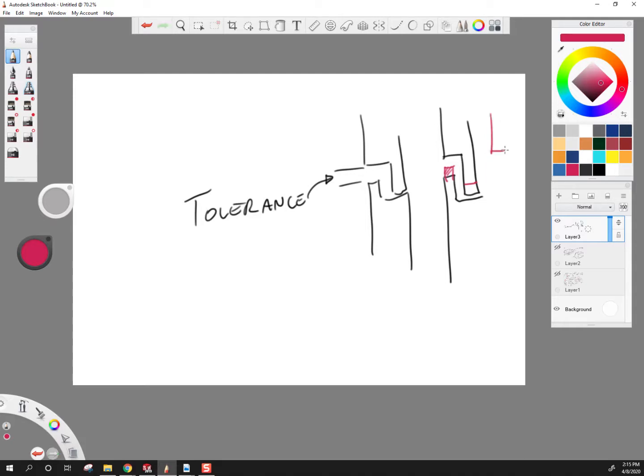in a worst case scenario, tolerance happens within a range, and often I believe a tolerance is plus or minus like a millimeter, or it might even be half a millimeter. I forget now. It's been a while since I've had to work with tolerance. Basically, it's designing for molding imperfections, and by leaving this gap here and knowing what this acceptable tolerance is, even in a worst case scenario, there will always be a gap here, or maybe worst case scenario is they will